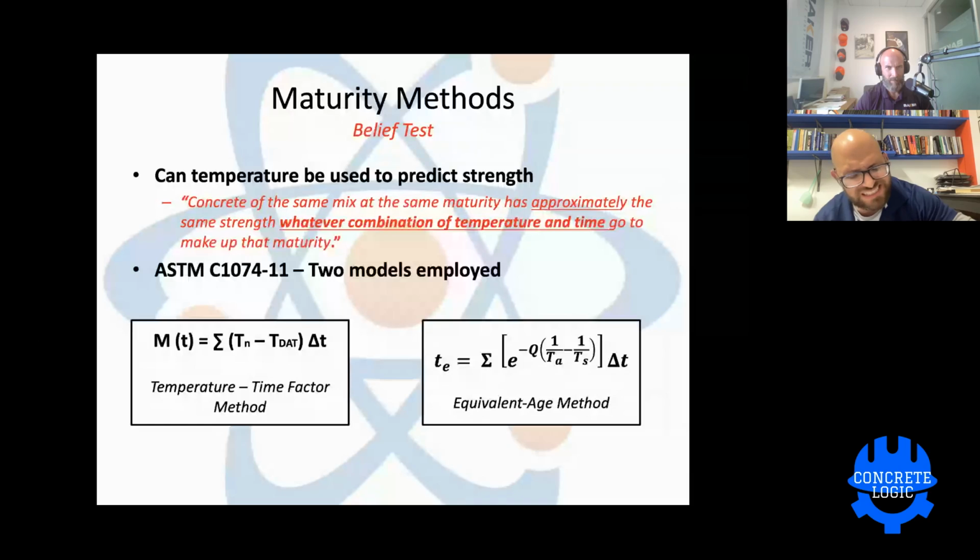And what those things tell you is, first of all, you can get it from the ASTM. The ASTM will tell you that if you're using a type 1 cement at a 0.47 water cement ratio, your datum temperature is equal to 0. No admixtures. Does anybody ever use that type of mix there, Seth?